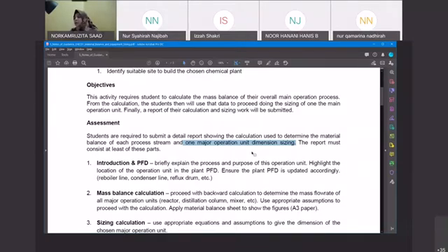You cannot control the number of trays or the number of stages in the column. You cannot control it, but you can still determine first what would be the number of trays involved if you have one condition of the feed, and then reflux ratio and the purity of your product, okay?